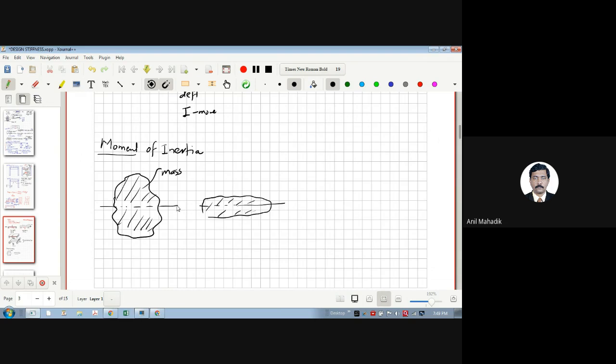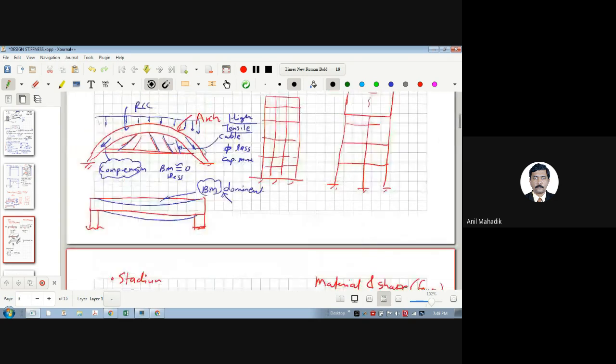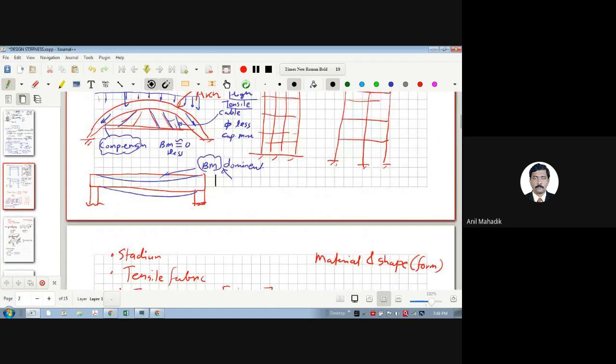But what is happening? Whatever the neutral axis is, the section rotates or bends about it. You know that whenever a section bends, there is a neutral axis, whenever we see these beam sections. If I try to show the bending in a beam section, you know that at the neutral axis it will not change its shape.